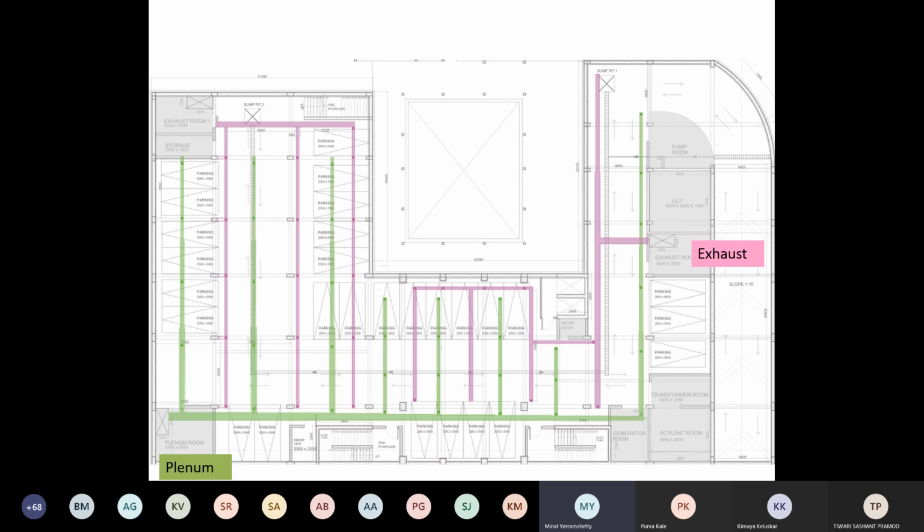So I'm saying A1, A2, then I am coming further where the car parking starts is my A3, and then the duct has a kind of a turn and then becomes horizontal. That is my A4. So assume that I have A1, A2, A3, A4 as a bay. Now, obviously, the duct which is starting from the point where it is taking a turn is housing the volume of all four, barabar hai? Then part of the air is given to A4. Then it releases the air to A3. This all happens in a matter of seconds, guys. But I'm talking about volume. Then it gives the volume to A2 and finally to A1.